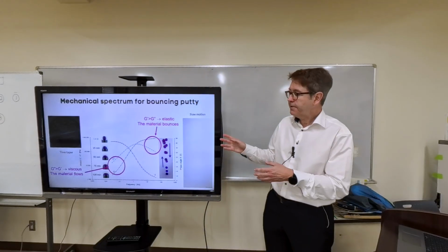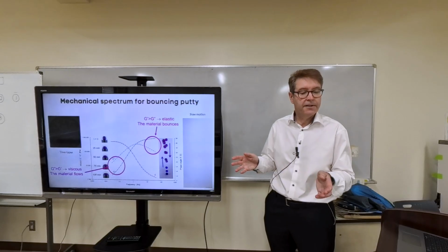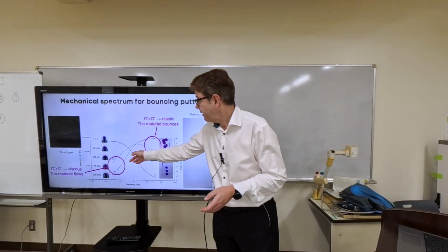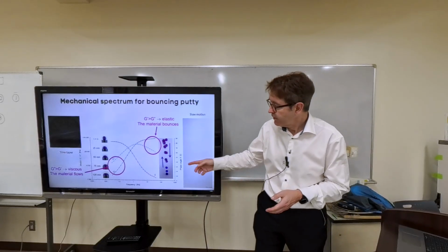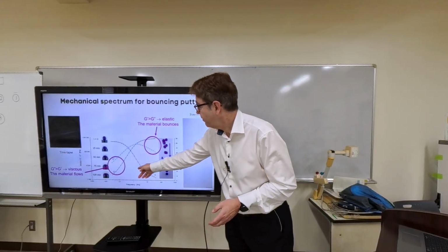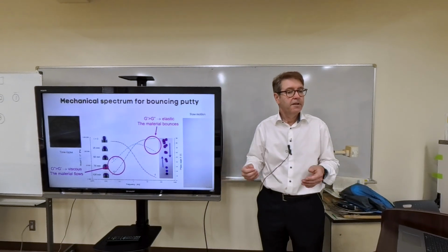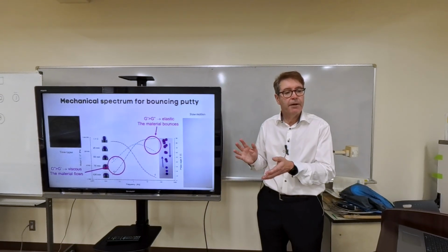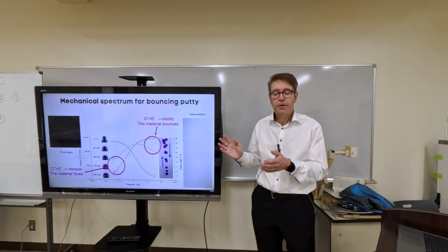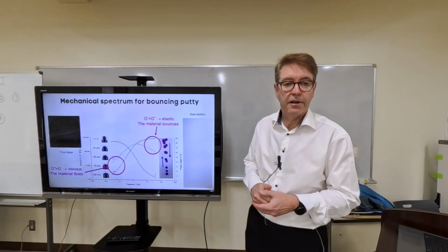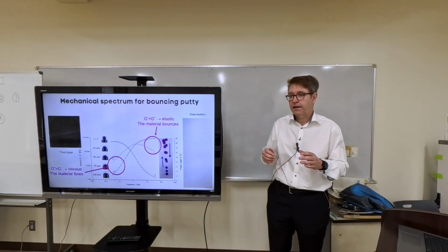So by this characterization, you can see if a material is viscoelastic, how viscoelastic it is. If you take where they cross, that's a typical relaxation time. So this one will take maybe one second or 10 seconds to relax. So you can get the typical relaxation time of a material as well. So this is a common way of measuring viscoelasticity when you have something that is more or less equally viscous and elastic.